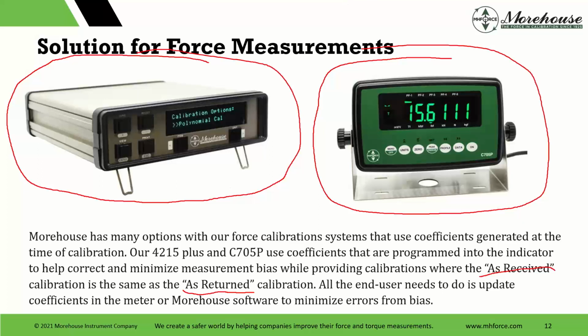Your cal reports stay in the same unit, and you can truly track that standard, not knowing how many times it was adjusted. Because those that are tracking their standards, as soon as it was 10,000 in 2023, 10,004 in 2024, 10,008 in 2025, and then you adjust it. As soon as you adjust it, that history gets really muddled and becomes difficult. Not impossible to trace, but super difficult for anybody that has done it.